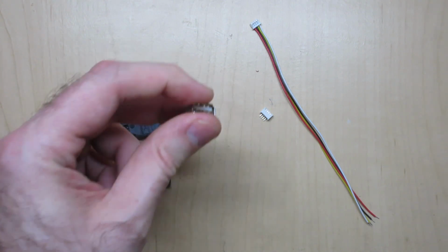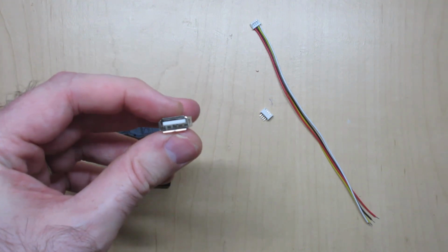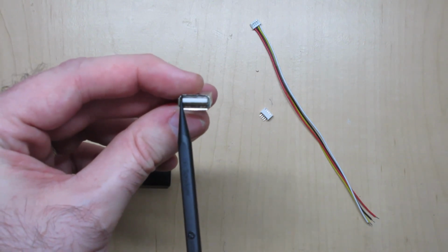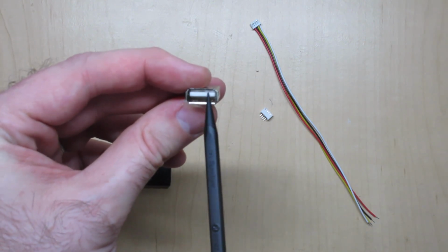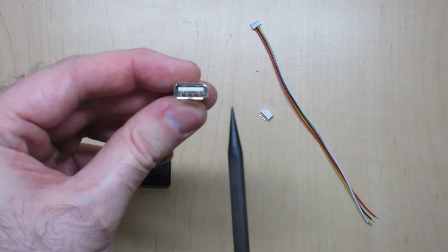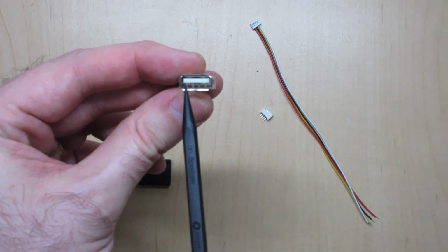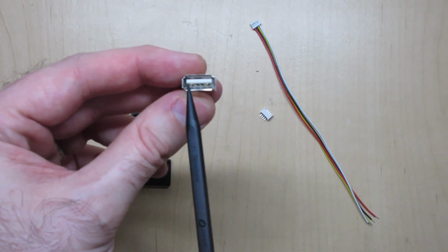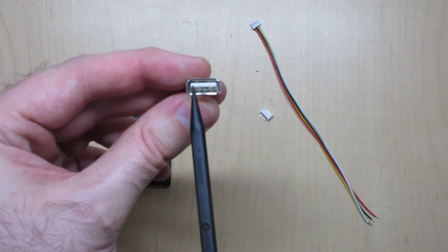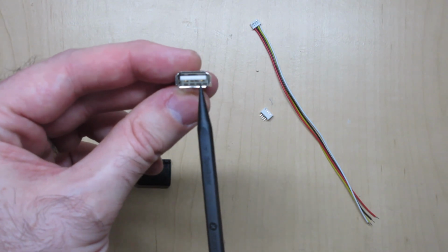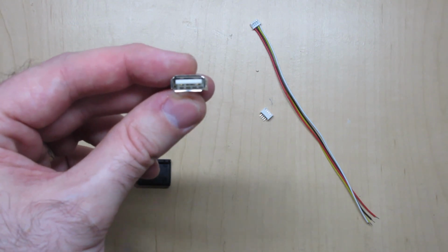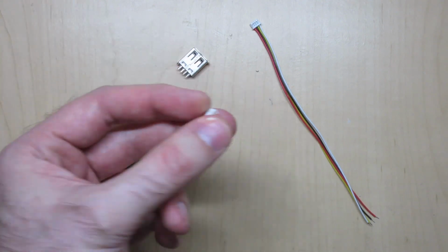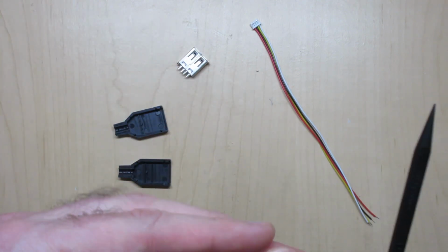So let's start with the familiar end, which is the USB side, and I remember this by holding the female end so that the plastic part of the connection is facing upwards. And then the terminals are enumerated 1, 2, 3, 4 from left to right. And that translates to plus 5 volts, D minus, D plus, and the ground, where the middle two are the data connections.